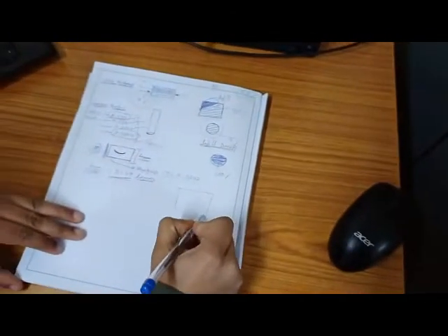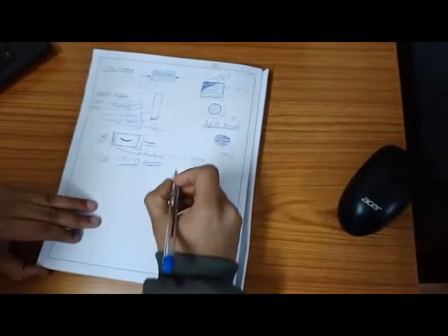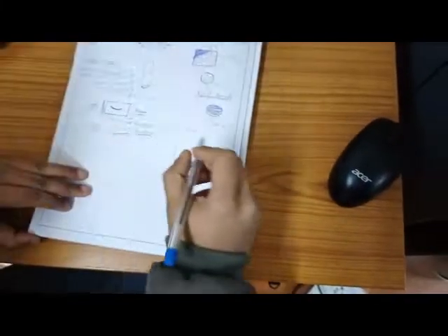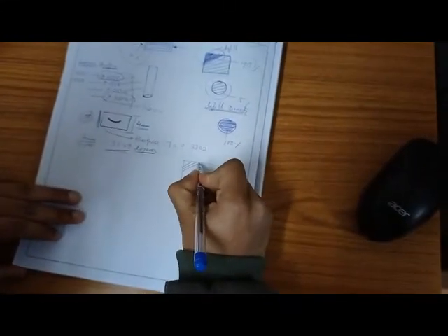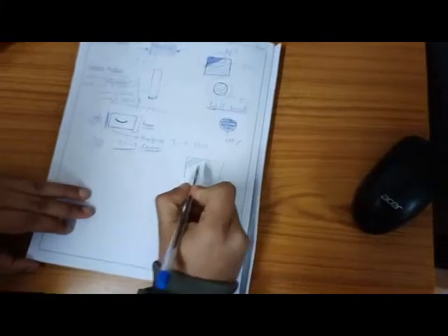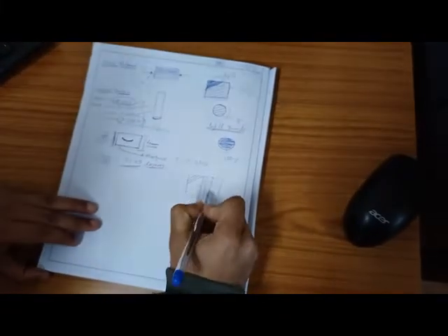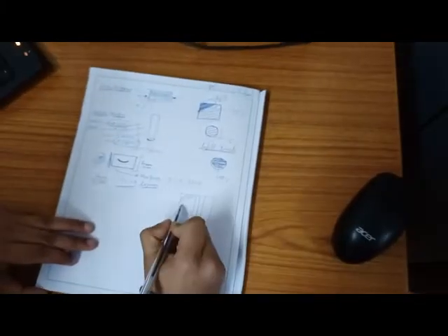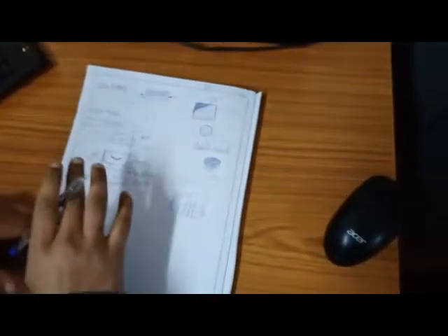So talking about the infill angle, again we have this option. This is the part, and it sets in which direction the nozzle head will print. We have selected 45 degrees here, so it will be in this direction. Suppose we select 90 degrees, then the printer will print in this direction. If we select 180 degrees, it will print in this direction. Fine, so basically it is showing us the orientation in which the nozzle head will print.